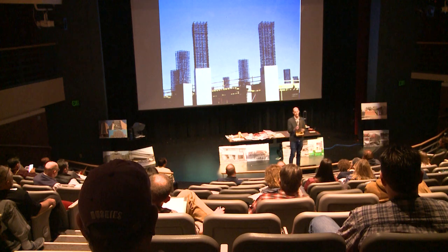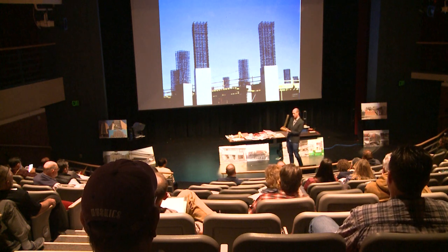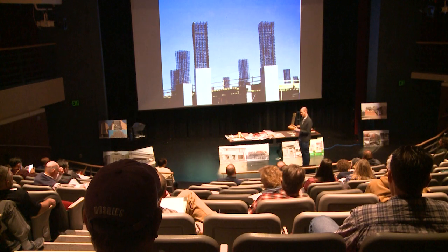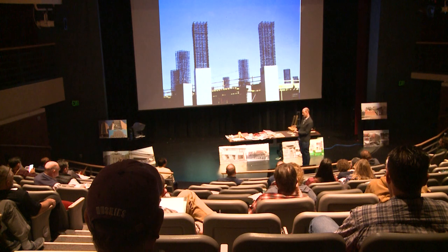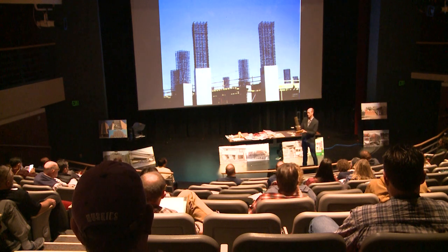And it's really a function of how large and frequent and how well detailed with the hooks the bars are. So here's a real quick physical, tactile example of a 1970 Uniform Building Code non-ductile reinforced concrete column on your left, and this is a 2003 International Building Code column.